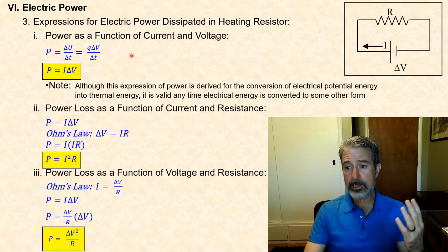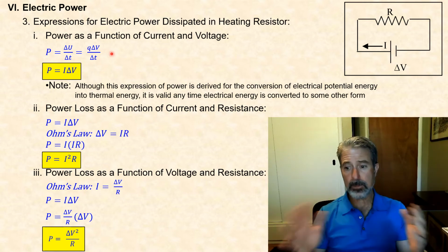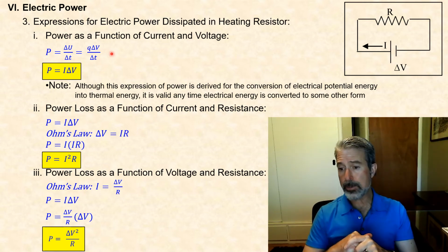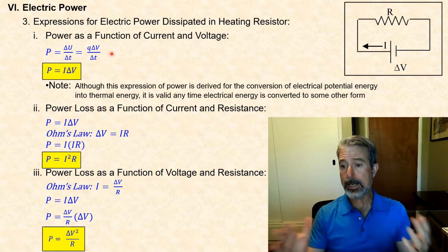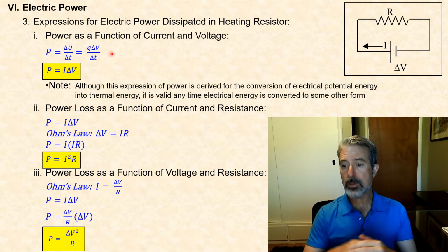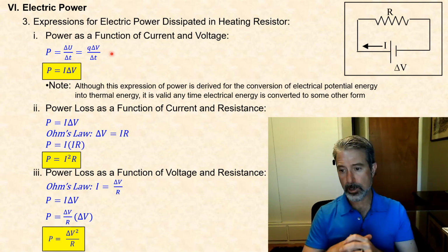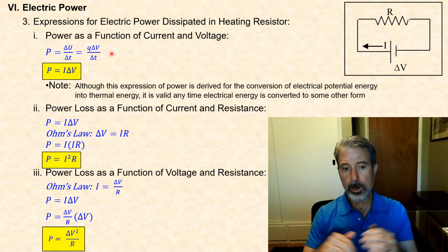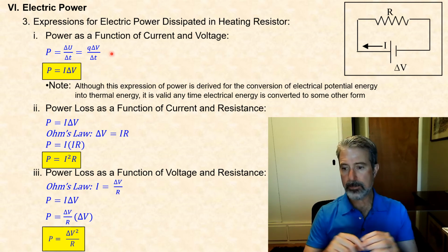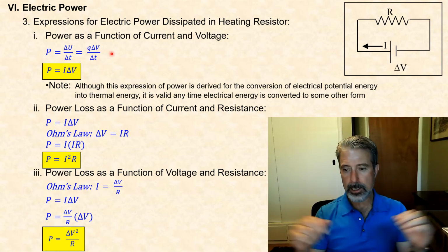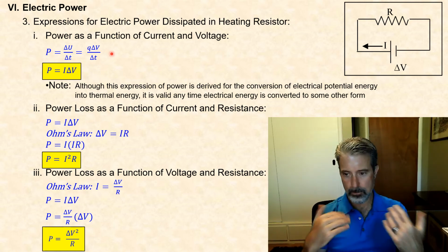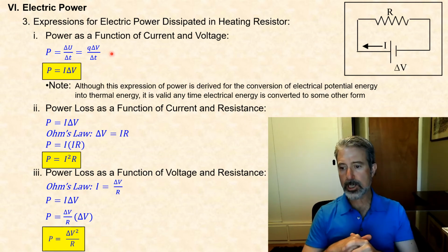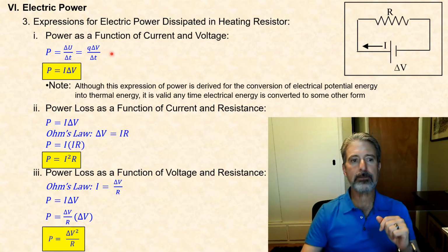So as we'll see, anytime you have electrical energy being transferred through conducting media, through wires basically, you have this I squared R power loss due to frictional heating. And this is unavoidable. Certainly the longer the conductor, the more resistance exists, the more I squared R power loss you're going to have.